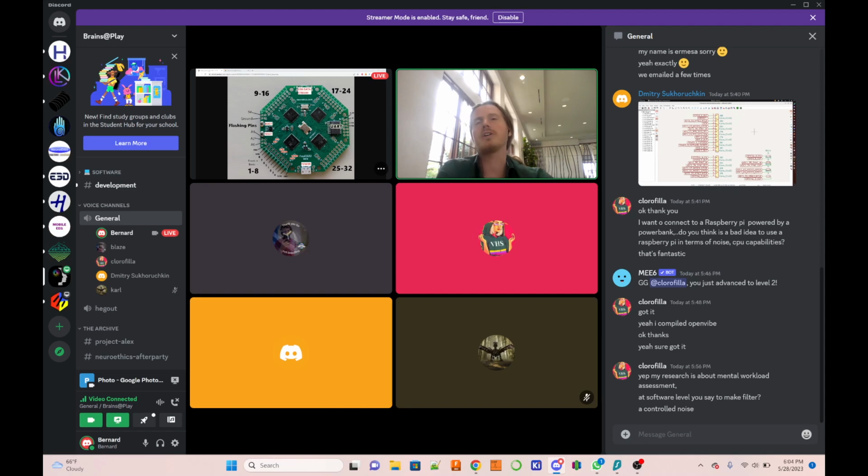Yeah. So now the other thing is, it is there to reduce noise. It is my experience that even when I don't connect it, I don't see a big difference. It will make a big difference if you are in a very noisy environment, which, in any serious EEG application, that's the first thing you do.